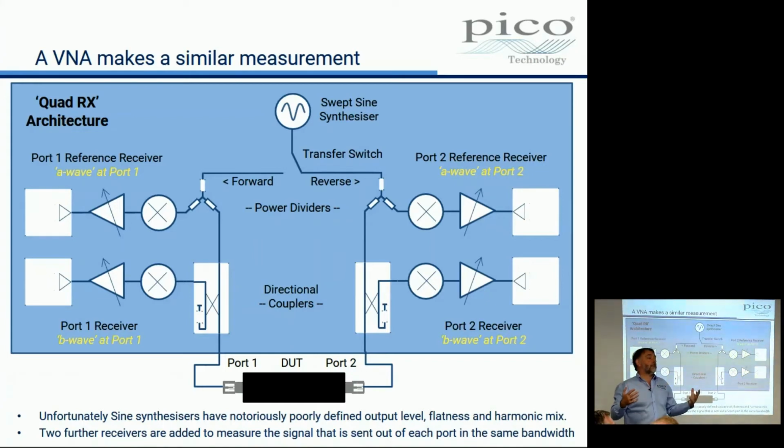It'll be a 1 megahertz signal of around the same amplitude as the signal that is being received. So the signal being received is this 3 gigahertz signal, but we've mixed it down to what's called an intermediate frequency, and we've made a megahertz signal that represents the amplitude.